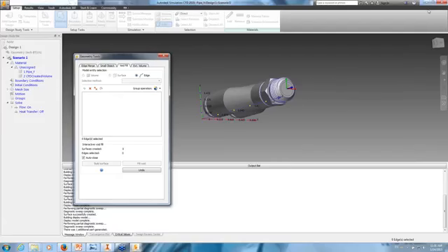So there are 2 workflows. If you bring in a cavity into CFD, it will automatically generate that extra volume for you. So I'm just trying to save you some clicks. Yeah, if that cavity is watertight. Right. And that's why you would add those caps to make it watertight, and then this volume that I just generated would be automatically generated, and you won't have to do that. Right. And sometimes you don't even have that edge. If you have some kind of spherical or rounded surface, you might not be able to grab an edge. And of course, then you can suppress those caps and get them out of the design.